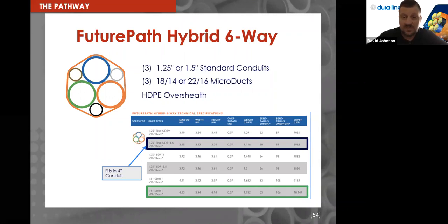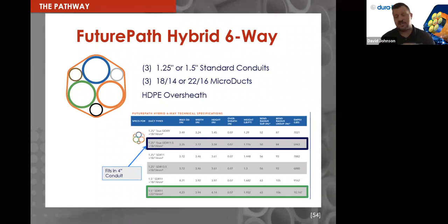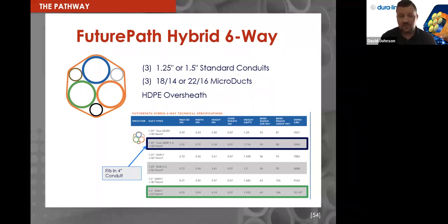So if there's 4-inch PVC pipe in the ground, a lot of customers are using Maxell, the fabric liner, which isn't a permanent pathway. They can tangle, and in that method you're still pulling in your fiber, so you're having to cut at certain spots and do a lot of figure eighting. Whereas this, as you can see, is a permanent pathway. You pull this into the existing 4-inch conduit, you've got 6 pathways. And you can couple those together at the access points, the manholes or the handholes, and then jet right through those locations and work your way backwards for slack loop. So it's an enhanced solution for our customers.